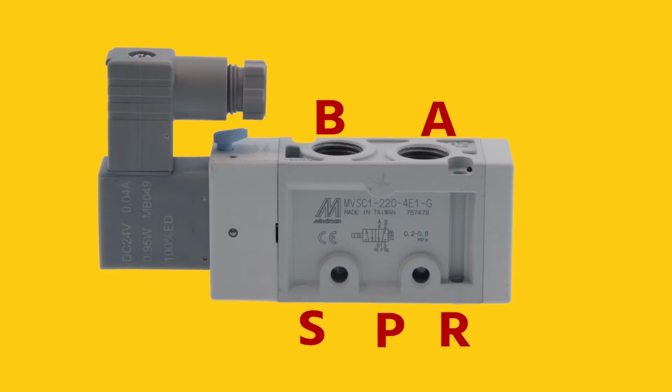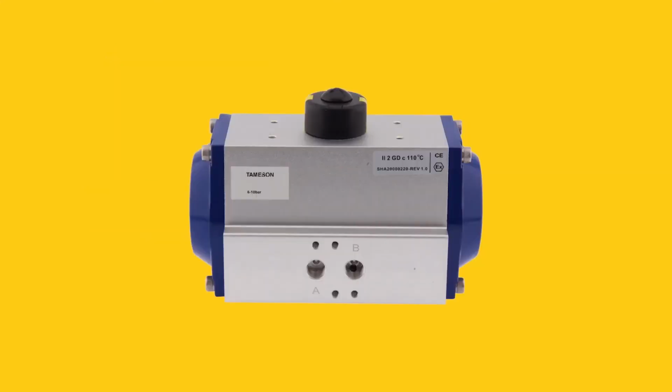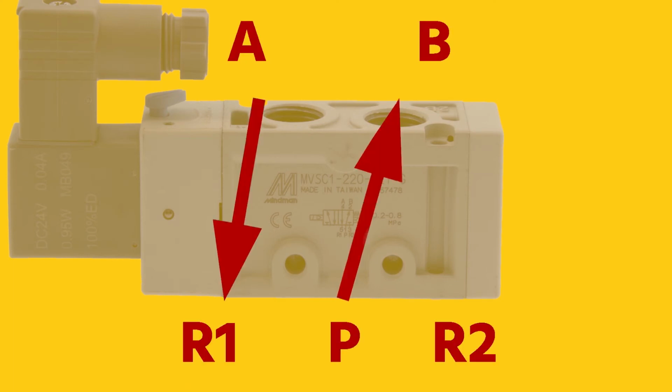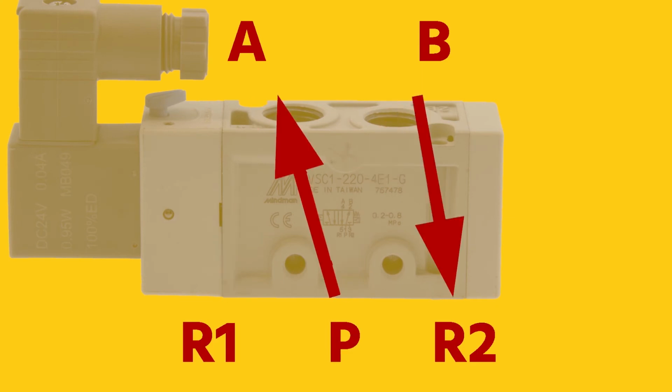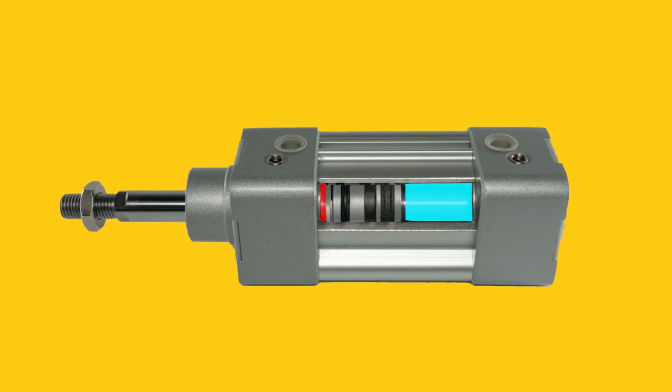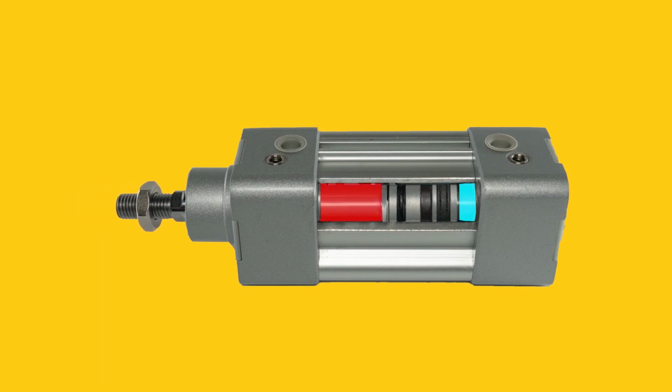Another example is a 5-2 valve. This valve has 5 ports and 2 states. These valves are often used in combination with a double acting cylinder or rotary actuator. The valves have 1 port to supply air pressure, 2 exhaust ports, and 2 ports to connect your appliance. The pressure port is always in connection with one of the 2 appliance ports. The other appliance port is connected to an exhaust port. With the example of the double acting cylinder, it means that one chamber of the cylinder is pressurized while the other chamber vents and vice versa.